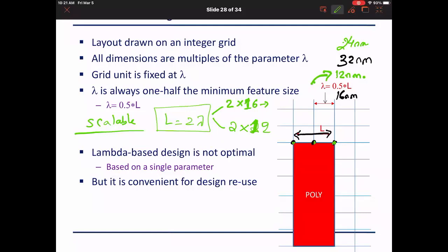Somebody said, let me reuse this layout which I drew in 32, but let me draw a grid on top of it and just say every 16 nanometer will now be counted as 12. Exactly like maps, not to scale. You can draw a bigger map, but instead of drawing a bigger map, they just tell you that your scale, lambda, changed from 16 to 12, and so on. Instead of enlarging or shrinking the drawing, we just say the scale changed.